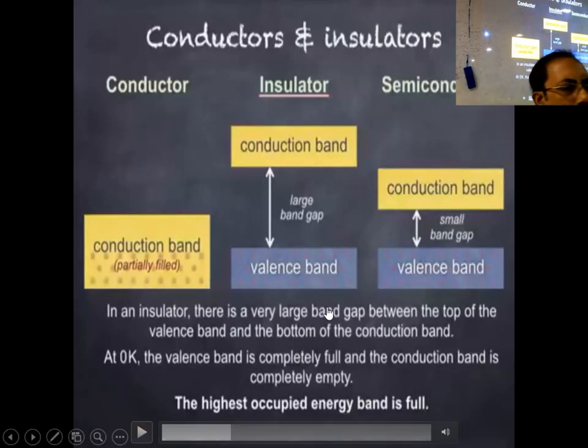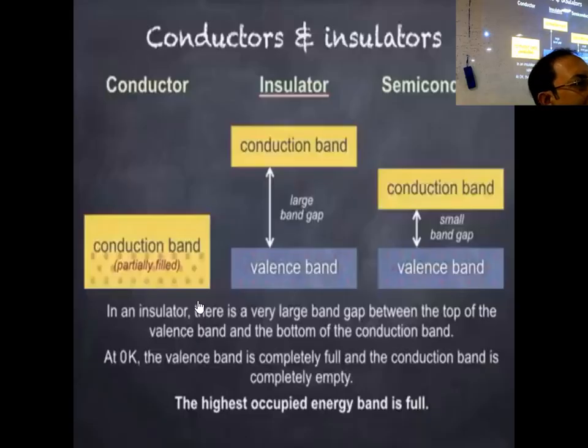Finally, another thing to mention, in the case of a metallic conductor, if you apply heat, the resistance increases, that you know. Why is it so? Because the different levels are all merged together, and when you apply heat, the electron movement becomes random, up and down. If it is irregular, then there is no current flow in a unidirectional way. The electron movement is random, and that's why the resistance increases.